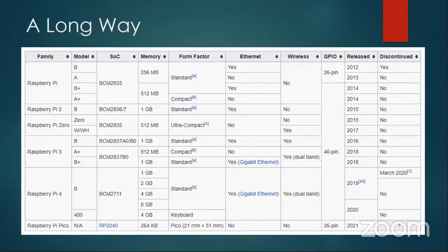But when it comes to Raspberry Pi 4, as I initially told, they keep marketing it as a credit card size computer. To keep the standard form factor, they kept the same size and, with a lot of risk taken, put in the processor. They have provided a steel heat sink, but it doesn't really work. You need to provide a lot of cooling to the Raspberry Pi 4 while it is running. Whenever you are in a meeting, sharing video content, or watching videos, it will consume a lot of power.